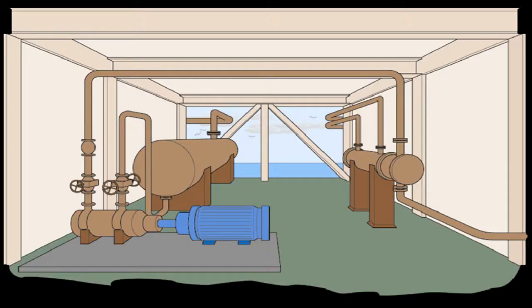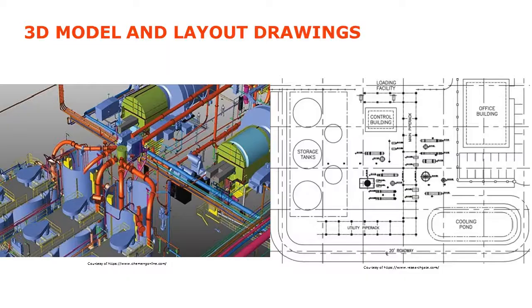Our next addition is the basic process plant. So now we've added a motor in blue, connected and coupled to a pump, likely a progressive cavity type, and piping to a vessel on the left and what appears to be a shell and tube heat exchanger on the right. This is the basic process plant. But to get there, we have to do a lot as mechanical engineers. As Masood had mentioned earlier, we are heavily involved with our piping team, who are mechanical engineers, with the 3D model and layout. So the distribution of equipment and piping and so forth is done by mechanical engineers.